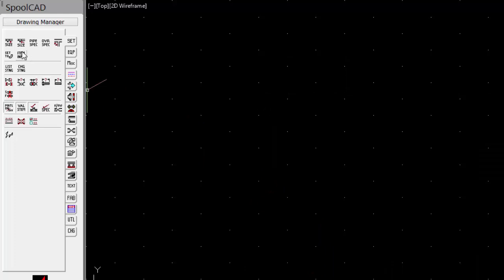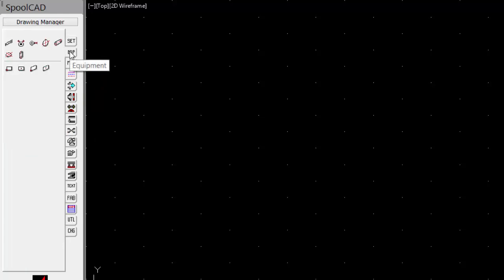We also have item information. We have some of our basic toggles for starting the software, whether or not we see a valve stem, spec checks. We have a line number tab if required. We can set and change it. And we can also set our isoplane setting. Underneath our Equipment tab, we can place some basic equipment symbols, horizontal vessels, vertical vessels.